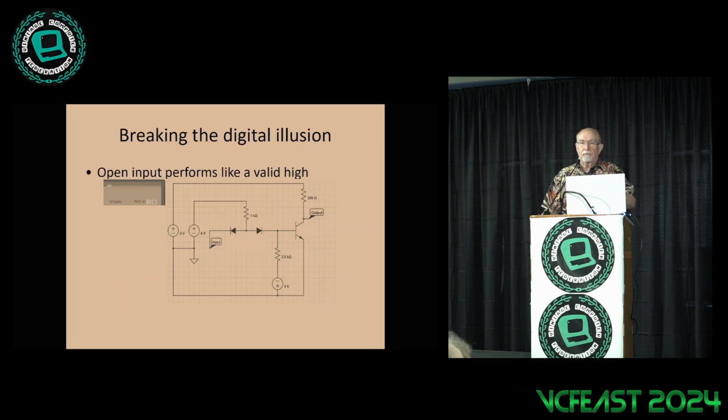So just very quickly on this slide, the point is that an open input or a high input, all the same. The only thing that counts to DTL is if you're pulling current down through the diode to pull that junction down to 0. That's all that counts, is taking it down to ground. Everything else by default is a logic 1, which means that you'll see a broken trace will look like a perfectly happy logic high state.